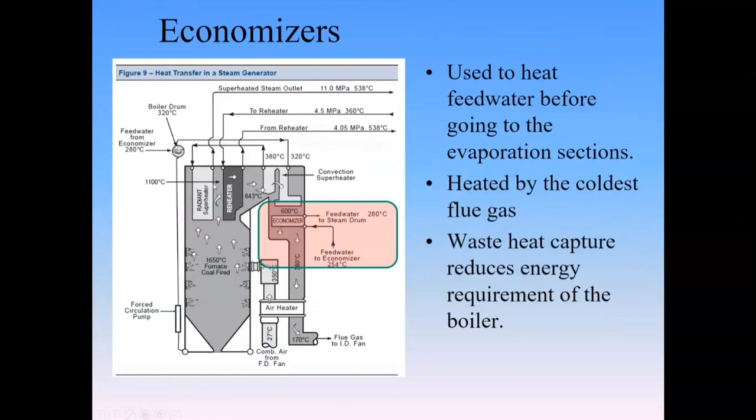After we've gone through the boiler a bit, we get to the point where we've lost some of that heat. And once we've lost some of the heat, the temperature has gone down, and we're no longer at the point where radiation is going to be our primary heat transfer mechanism. Okay? And so we may be going through sections here where we have tubes that are either bare tubes or fin tubes for picking up heat, and the economizer might be an example of that.